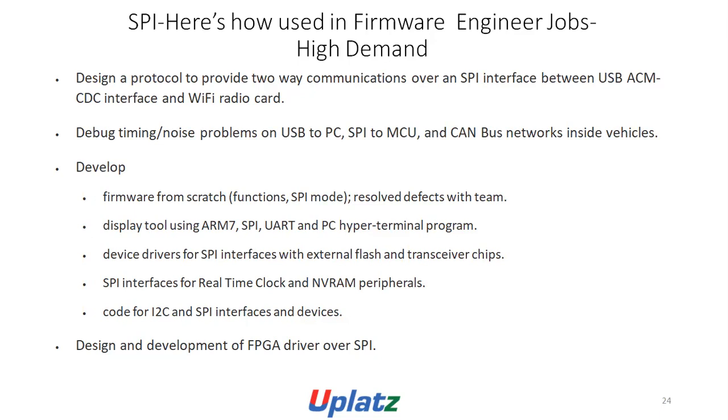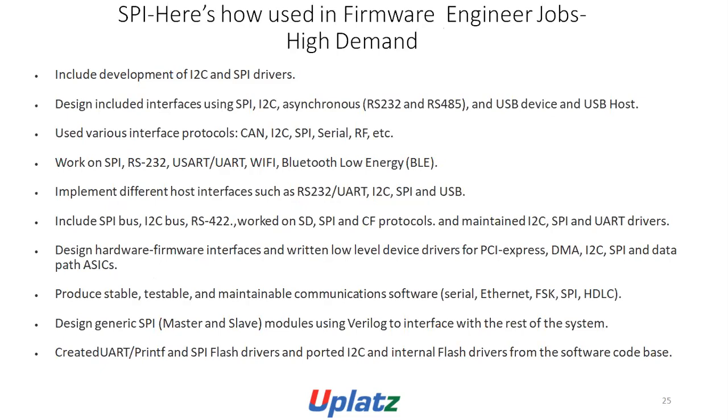Device drivers for SPI interfaces with external flash and transceiver chips. SPI interfaces for real-time clock and NVRAM peripherals. Code for I2C and SPI interface and devices. Design and develop PGA driver over SPI. Include development of I2C and SPI drivers. Design included interfaces using SPI, I2C, asynchronous RS-232 and 485, and USB devices and USB OS.